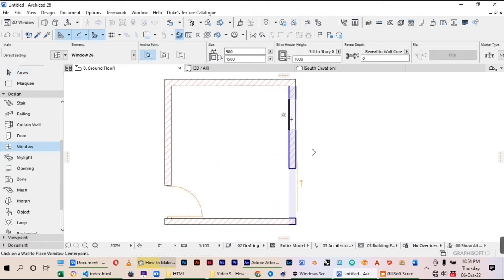Let's see the size that we have. Hitting on M, and you can see we have 2500. And most of our glasses are 4 feet in width. So you try to think how many glasses can fit here. If you have 2500, to fit them equally, you need about 800 and something. So those are 3 divisions.